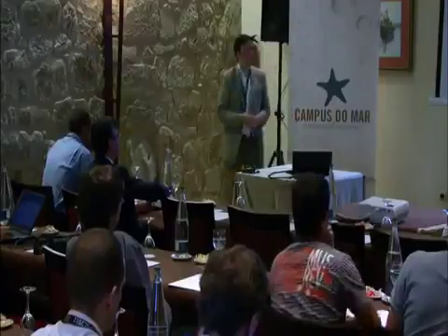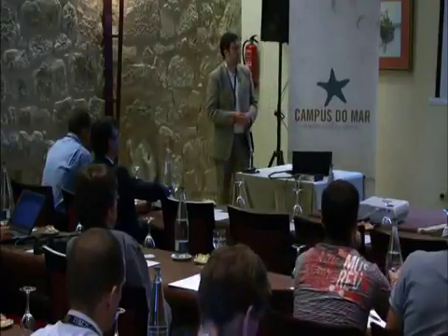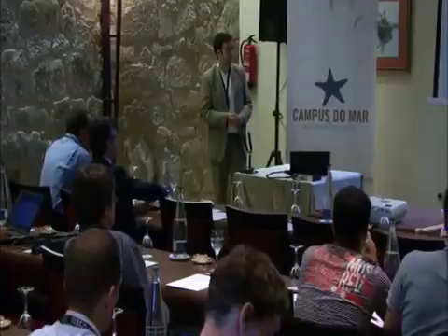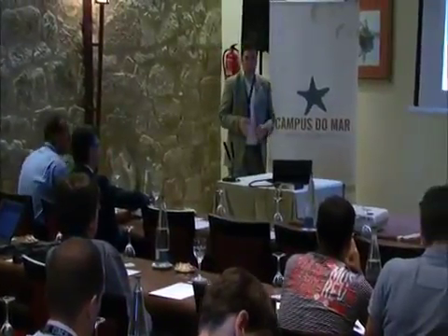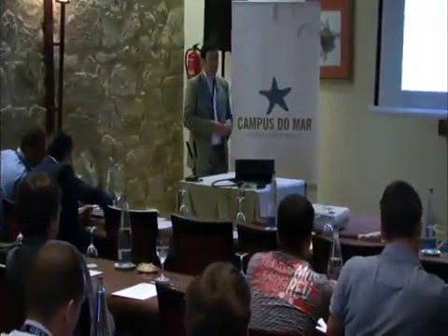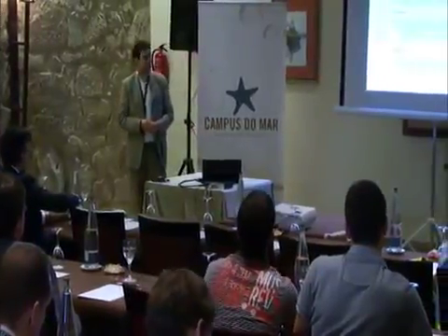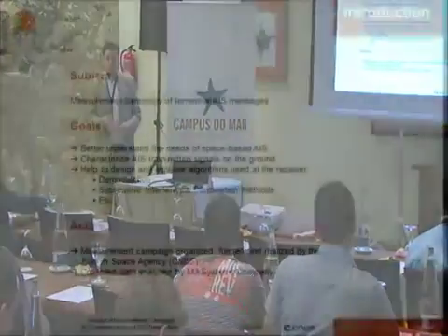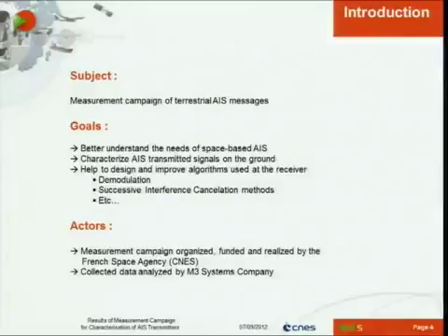So the subject of this presentation is a measurement campaign of terrestrial AIS messages. The goal of this campaign was to better understand the needs of space-based AIS thanks to a characterization of AIS transmitters and transmitted signals, in order to help us to design and improve algorithms used at the receiver, such as demodulator or successive interference cancellation or AIS burst detection.